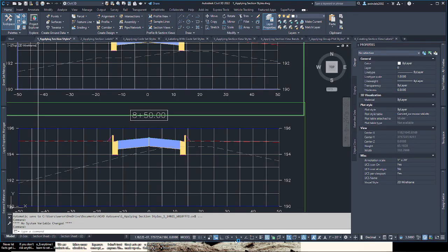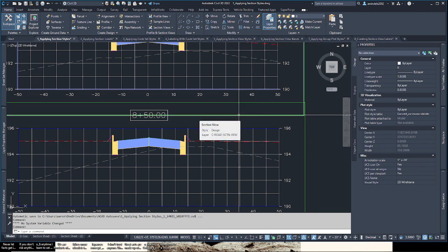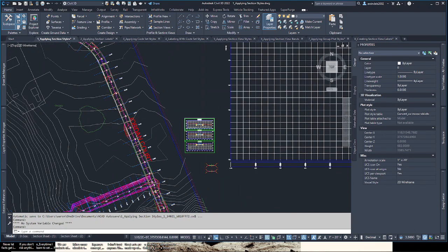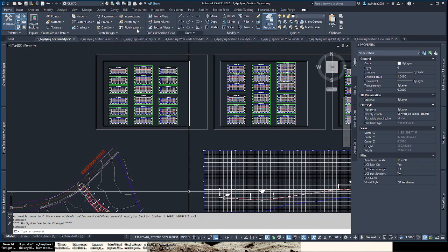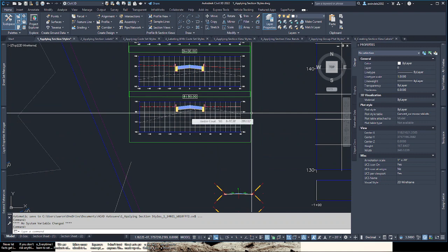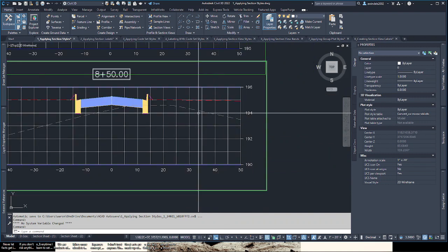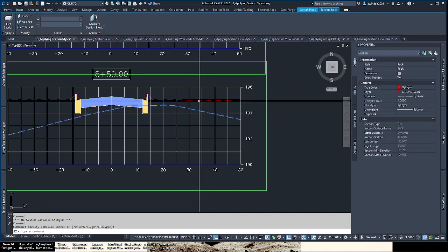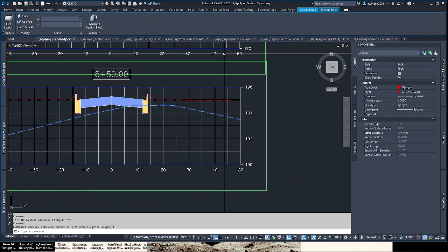Okay. So continuing on with exercise 11.2, we're learning about applying section labels, and we're going to go to the lowest section view and click edit section labels, what it says on page 210, which will be these section views over here still. It's a little unclear on that, but it shows you a picture on 212, not these multiple section views up here. Let's stay with these, and we're going to the lowest section view, which is to the south here, and we're going to click on the rock section, which is this section right here, any way you can with your cursor. And as you see in properties,